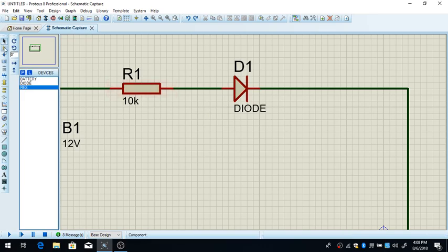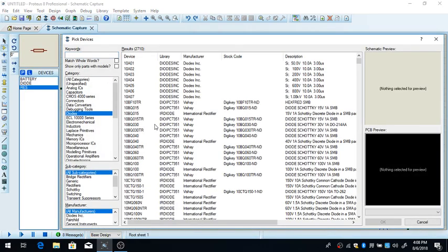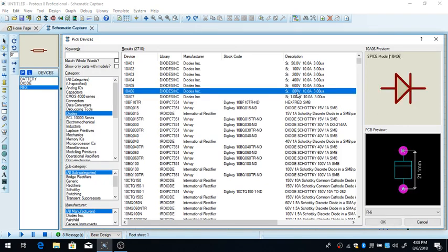I mean, when I go to the library here, you go here to the diodes, you can see the specifications of the diode. So for example, this 800 volts. Here we have a device called a diode. This is the type of diode, 10A06. Here it says that this is a silicon diode. This 800 volts is the peak inverse voltage, the biggest amount of voltage that can be reversed. So if you put more than 800 volts in reverse bias mode, then the diode will explode.